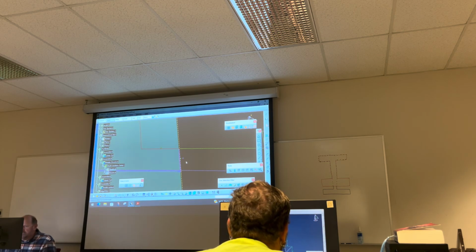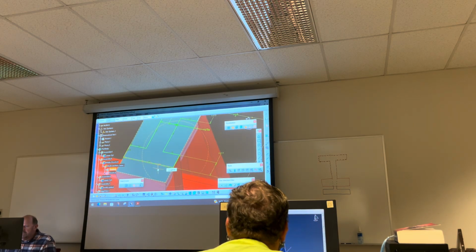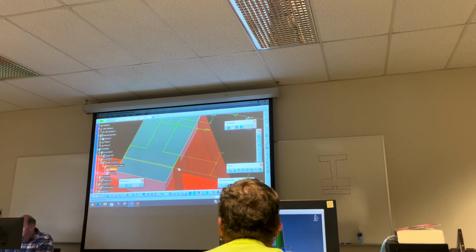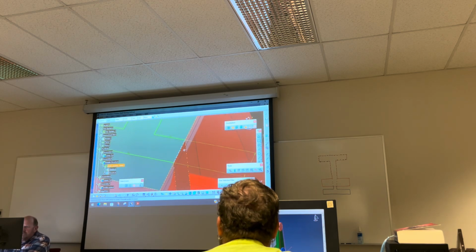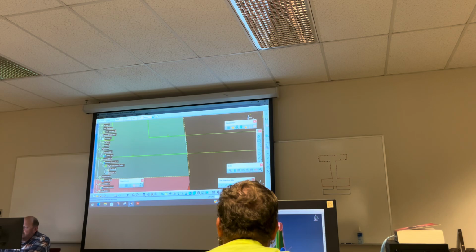Do a Control C on this. 1.1. Oh yeah, there we go. That's locking it out. Because when you go to build this, if you get an error with the fillets, it's basically a pointer saying there's something going on where it transitions into the rest of the part. Because I've assembled this part together right now.